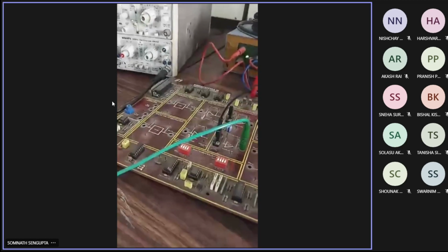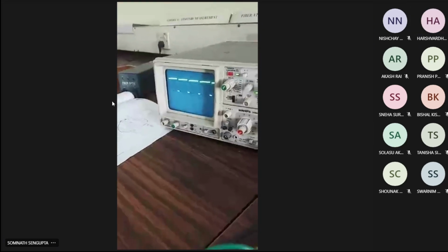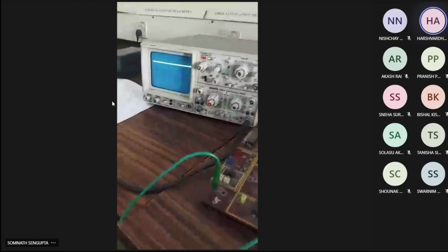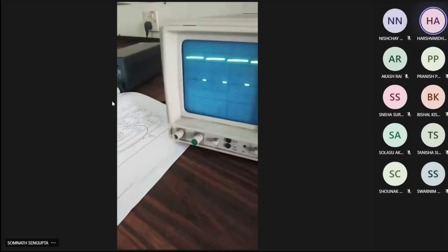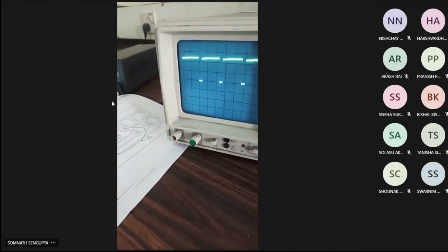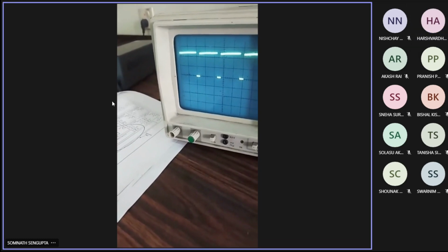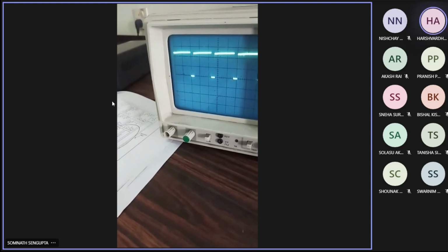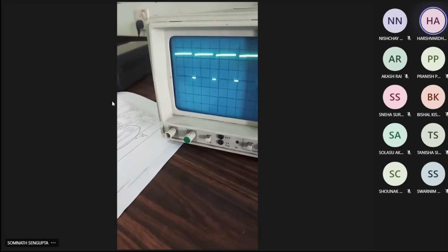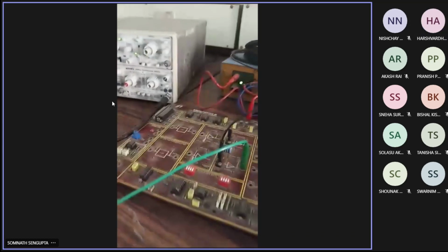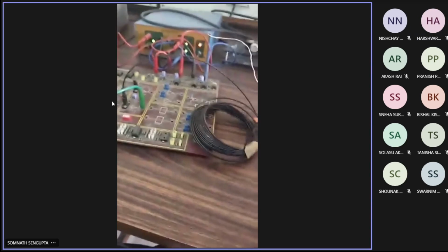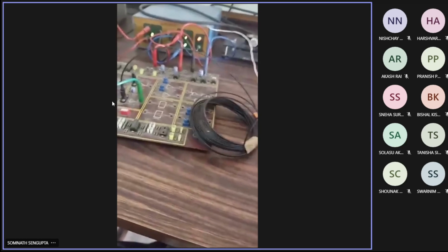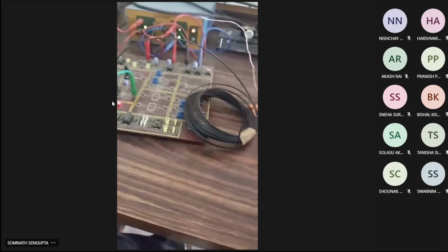For 10 meter, what is the output voltage? Yes, sir. 0.24 volts. Okay. Sir, once can you explain how did you take that 0.24? I understood 1.2, but how did you take 0.24? So previous one was 1.2 volt. Yes, yes, I understood that, sir. Previous one was for 0.5 meters. Because of exponential decrease in the length, e to the power minus alpha L.